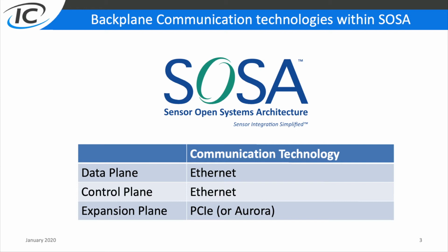VPX systems today mainly use Ethernet and PCI Express. Ethernet and PCI Express answer various interconnection needs. For example, SOSA defines Ethernet as the protocol to use for data and control planes, and PCI Express as the protocol to use for the expansion plane.